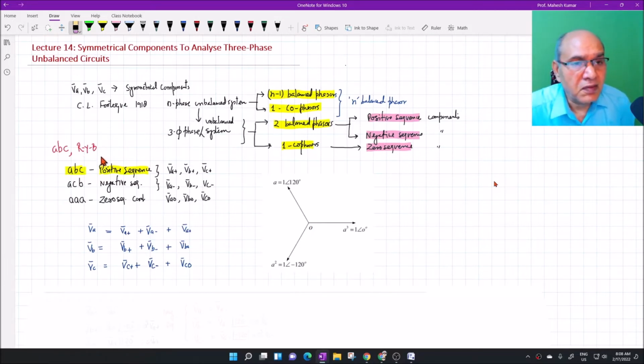If you open the cable, you will see the three-phase system cable has 5 wires: red, yellow, blue, black, and then there is also green wire. So red is for phase 1, that is A, the yellow is second phase, the blue is third phase, RYB, and black is for neutral, and green is for ground.